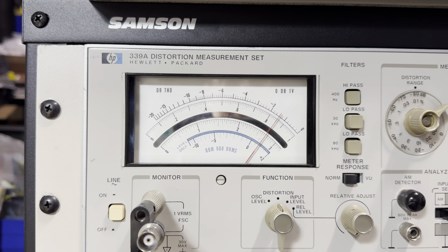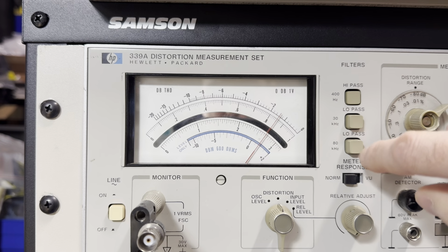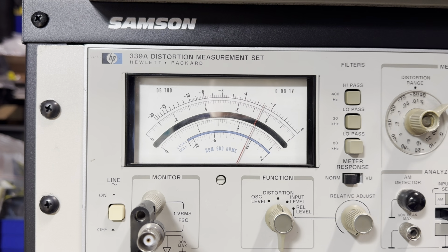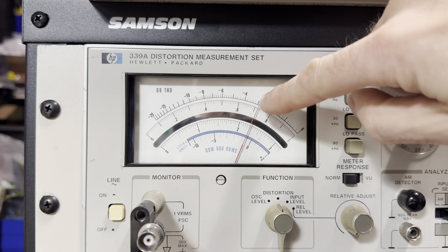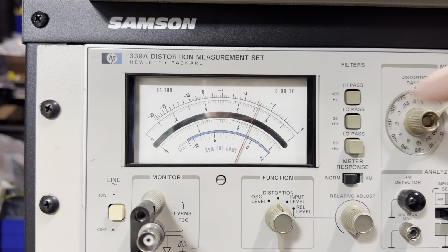So anything that we remove by placing this filter in is going to be signal levels that are high enough that are due to noise. We can bring that range in even further and go to 30 kilohertz. Even 30 kilohertz, we're talking about the 30th harmonic of 1 kilohertz. Again, we picked up some more. We took out some more noise, and we've got an even greater measurement there, sitting at minus 83 dB now,